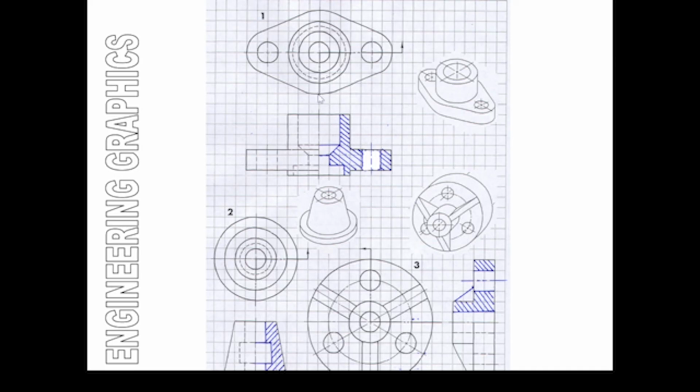In this particular case, we are looking at just a partial sectional view here, where the cutting plane went only about that much, and we have removed that quadrant there, and we are revealing the details of what remains behind. Something similar here. We are removing a quadrant there to show the inside of that particular part.